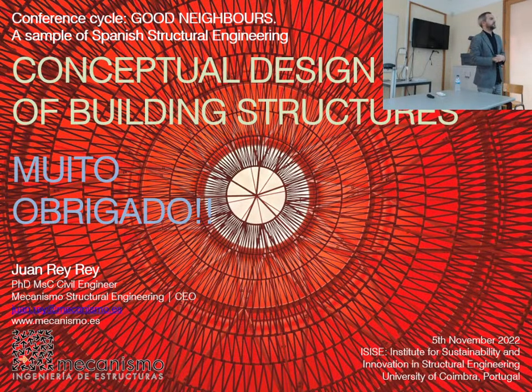Yes, it's only a matter of time in the construction process, because since it's faster to build above ground levels than below ground levels, by doing this you can finish the 5 or 6 floors you have above ground, and you can continue to work with the services and the finishes, placing windows, while you keep digging and constructing. So at the end of the day, the time you have for constructing the building is less in that way. This is the only reason for doing that.